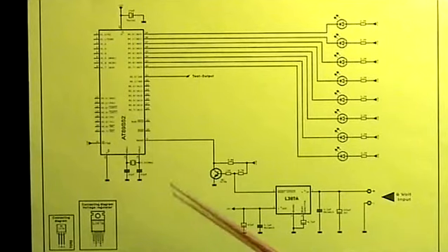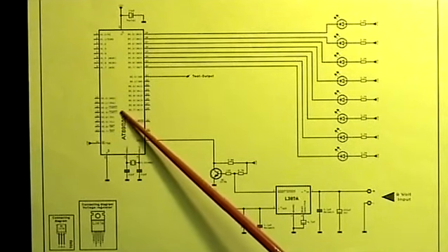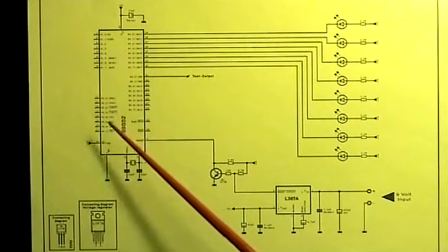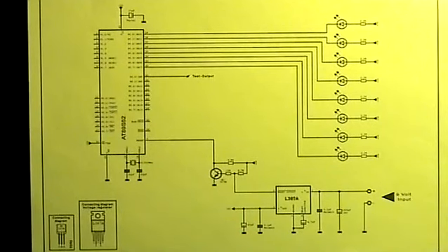The focus is on the AT89S52 microcontroller here in the PDIP-40 design. I connected the 8 LEDs to ports P0.0 to P0.7 via current limiting resistors of 2.2 kilo ohms.